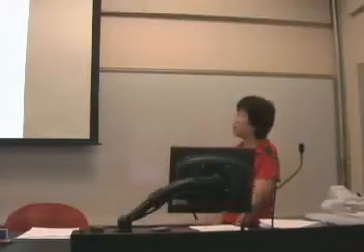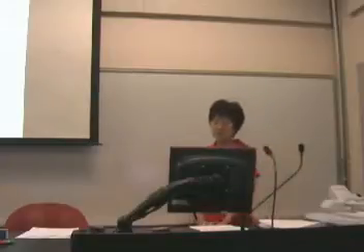And you can do the polynomial interpolation using MATLAB. There are already some built-in functions there. This is a simple example that shows how you can use the clamped end condition to solve Runge's equation. This is Runge's equation. MATLAB also has the built-in function interp1 that provides a number of different types of piecewise 1D interpolation. This can be nearest, linear, spline, or pchip.